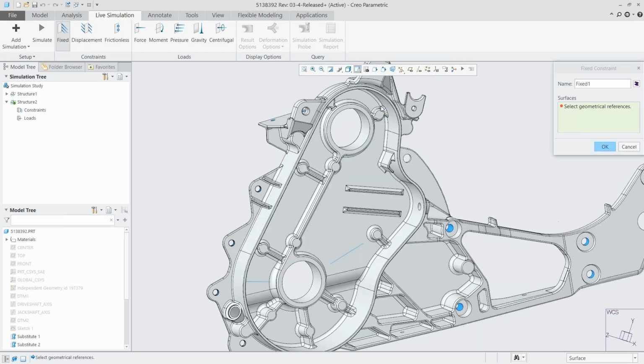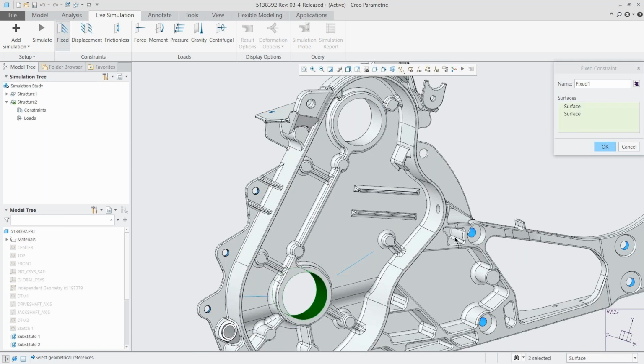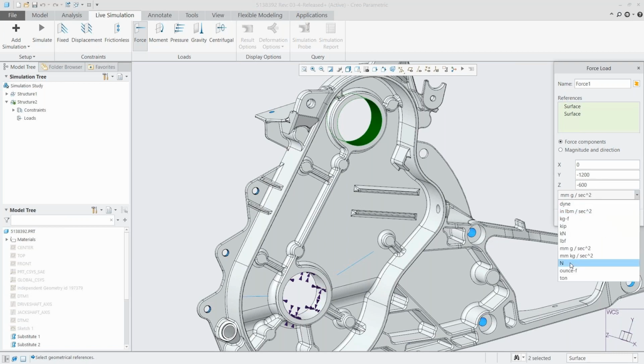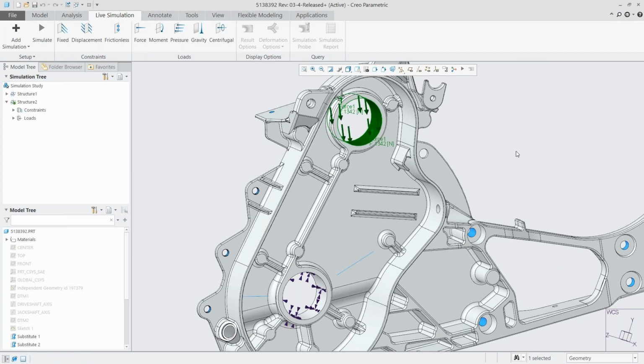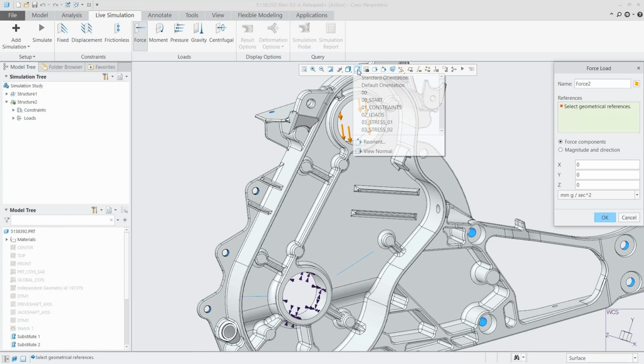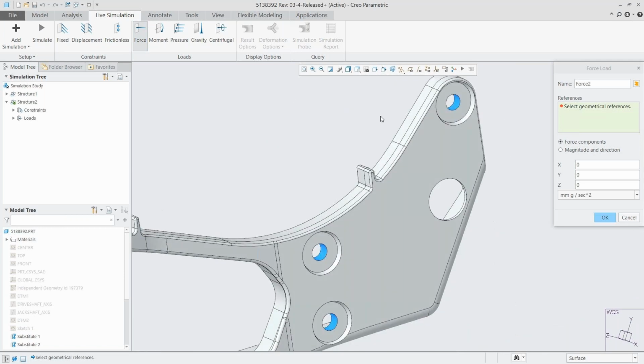With that, we're going to start to set up our study. So get in, maybe start to define some materials for our part, and we can move into defining the structural parameters for our part. That first starts with defining constraints by fixing certain surfaces. I know maybe with this, I have a certain bar that I can't have this part move around. So lay that out. And then after that, we'll just go and select the areas where we want to apply our loads. And this is just normal, and that's how we'd go through in our normal traditional simulation process.